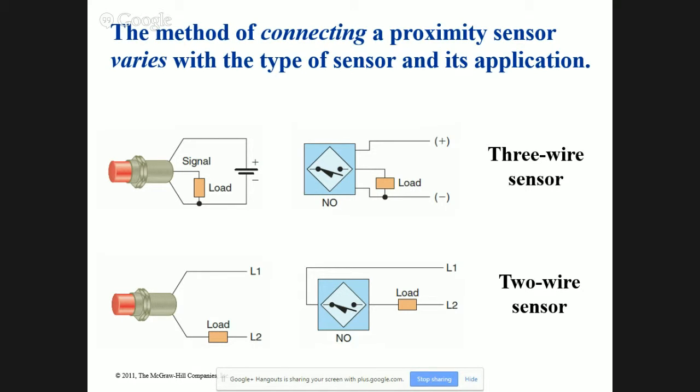Now, a 3-wire sensor, you've got a hot, some kind of ground, and then a signal, right? Well, typically a 2-wire sensor, they're not very big, and I'll tell you why. Because of how they actually work: you don't see it, but power comes in here, and then the little sensor uses just enough and bleeds it off.